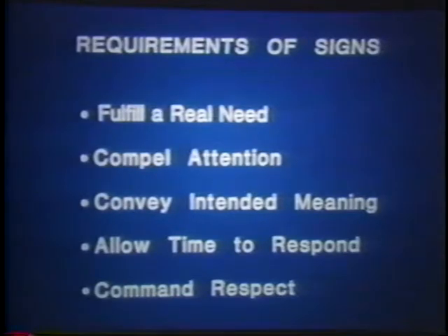Before signs are placed on the roadway, there must be a real and demonstrated traffic control need for that sign. Once a sign is placed, it is very difficult to have it removed, so careful placement is essential. For the sign's message to be read, signs must first get the driver's attention. The time necessary for the driver to respond to the message of the sign is usually provided by one of 2 ways. Either the sign must be large enough so that it can be seen in time to respond, or the sign must be placed well ahead of the needed action.